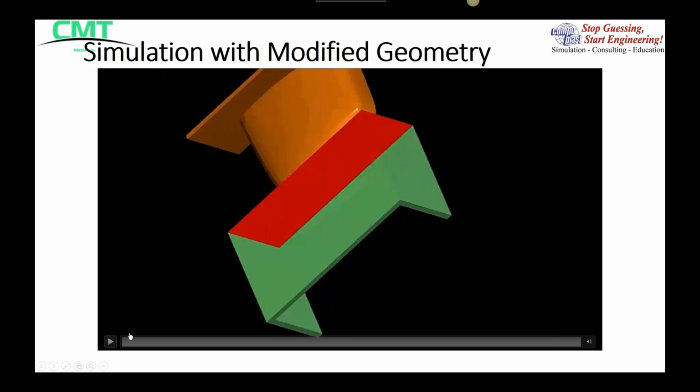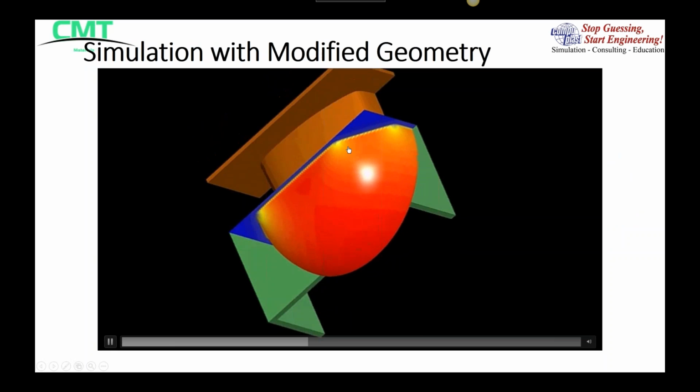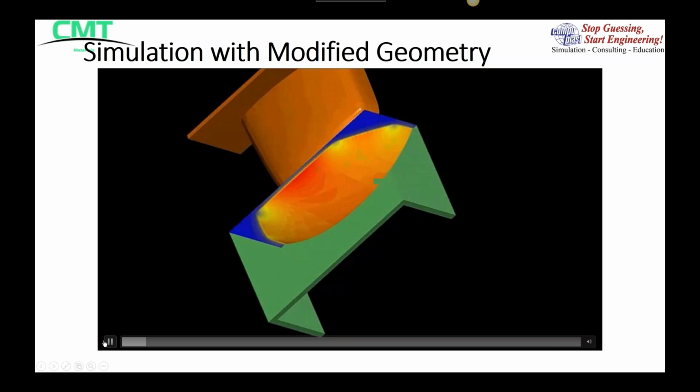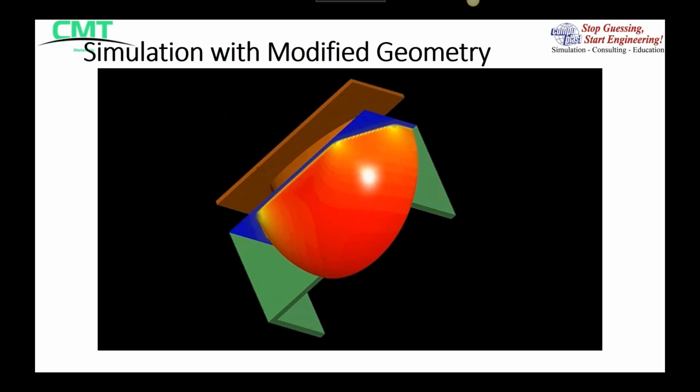And then when you go to build it, you have a greater confidence that by removing this material from being included, there's no excess material to form a web or wrinkle on the part, and you end up forming the part properly by taking that material out of play.